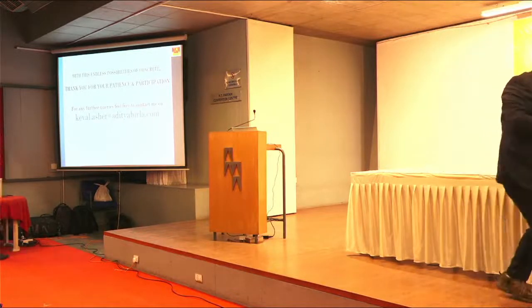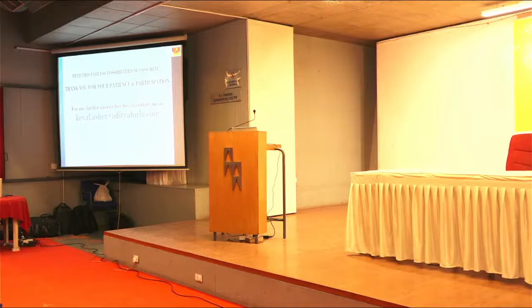Sir, you said about 3D printing concrete. So there are hollow spaces in between. What is the resulting durability and strength of the concrete? The mechanical properties have proven that it gives around 50 to 60 megapascal of strength, so strength is not a factor here. And as I have told you, the design for 3D printing is based on yield stress. A lot of calculation goes into it, and it is made in such a way that durability is not affected. The hollow portion acts as a barrier. Sound insulation or other insulation can be done if it is kept hollow, and there will be no effect on the strength or durability.